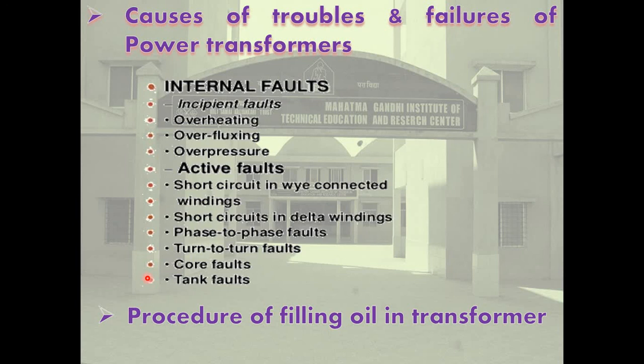Don't fill oil from storage tank into the transformer directly. Fill dry oil from storage tank via the vacuum filter into the transformer tank. Take oil from 200 kg drums into the storage tank or mobile tank trailer and dry the oil by circulation through the vacuum pump, and then fill it into the transformer tank as per 1 or 2.